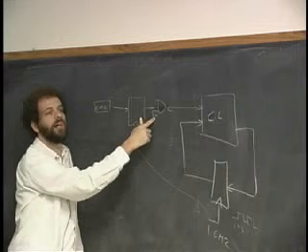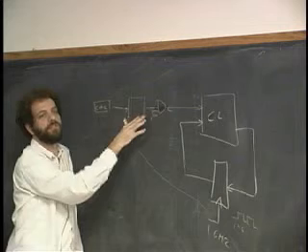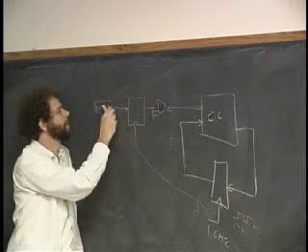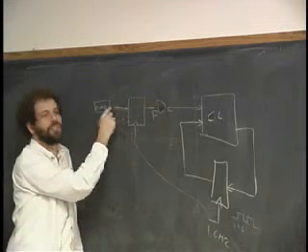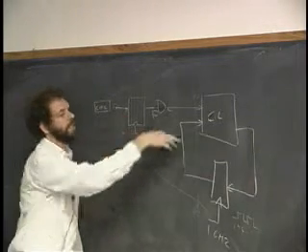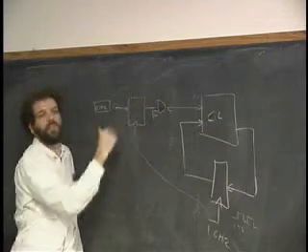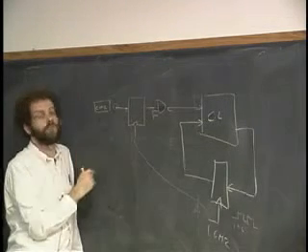So I could turn this off for 100 clock cycles after the person has pressed the button to wait for this to happen. And I could put a gate in here to not allow new button presses to come in during that time. And so I could set this off, and it could think about something else for 100 clock cycles, and then I can look at the output. That's a viable way to do it.